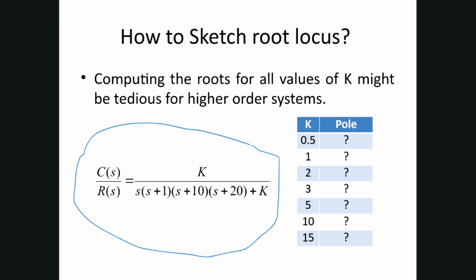It is fourth order, right? 2, 3 and 4. So the order of the system is 4. So how many poles will we have? We'll have 4 poles. Now let's take a similar approach, the approach we have taken for the first order system.